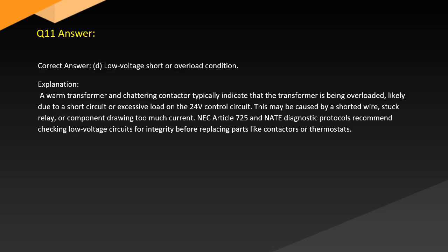Answer. Correct answer: D. Low voltage short or overload condition. Explanation. A warm transformer and chattering contactor typically indicate that the transformer is being overloaded, likely due to a short circuit or excessive load on the 24-volt control circuit. This may be caused by a shorted wire, stuck relay, or component drawing too much current. NEC Article 725 and NATE diagnostic protocols recommend checking low voltage circuits for integrity before replacing parts like contactors or thermostats.